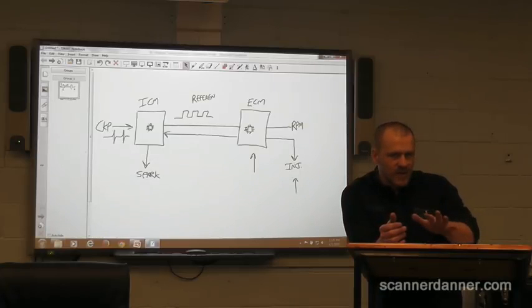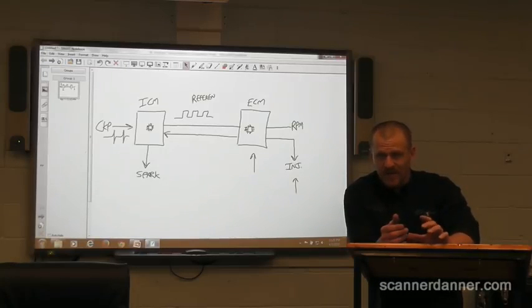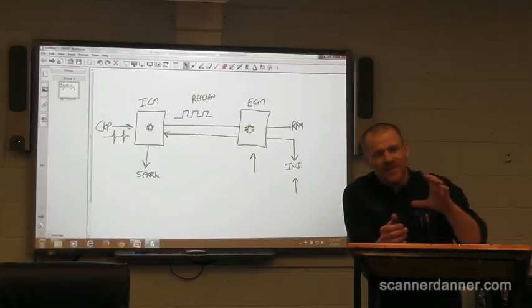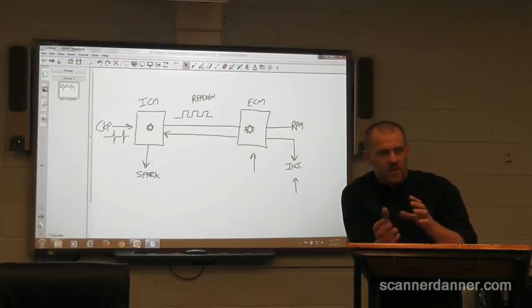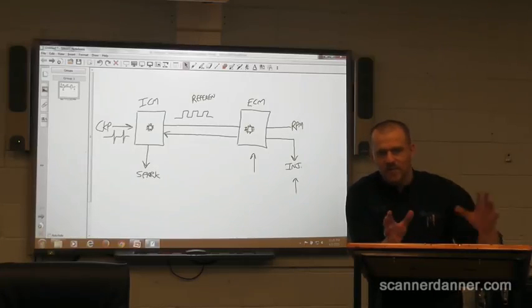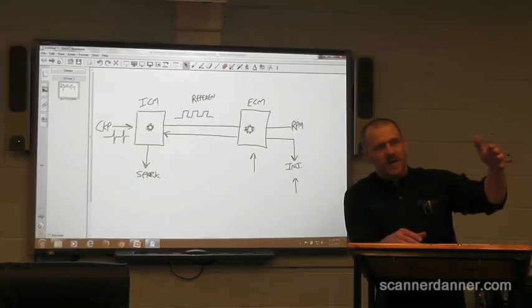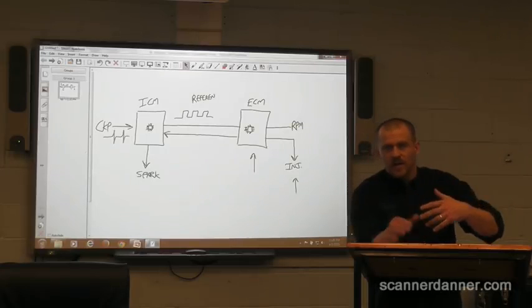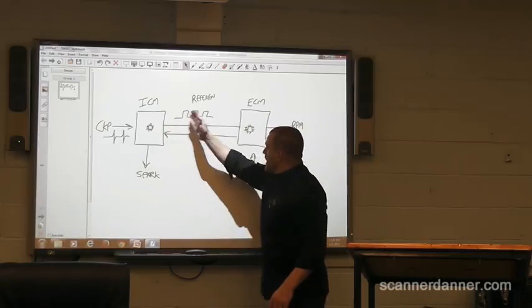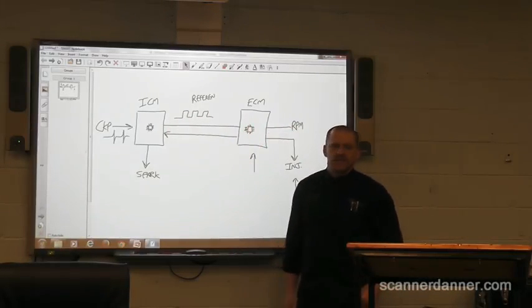A perspective you guys need to have with your ohm meters: your ohm meter is the battery. When you do ohm testing, you have to have the perspective that this ohm meter is my battery for this test. So now any other voltage source cannot be there when we're using the ohm meter. So we need to isolate the circuit. We need to disconnect both ends here and here to do proper resistance measurements.